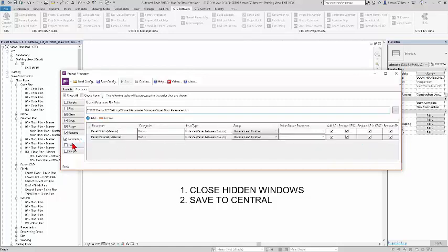My final option that I'm using is for parameters. I'm going to go ahead and add 2 project parameters to my project, adding them as instance properties. I can vary between groups, grouping them a certain way. I can source their value from a parameter that already exists on the categories that's being used in this case. I can also add the source, the schedule column, into a Revit schedule, a specific schedule if it's already being used there. It'll add these parameters in place of that source parameter. And I can do things like removing the source parameter, replacing it, and then deleting that actual original source valued parameter out of my project as a whole.